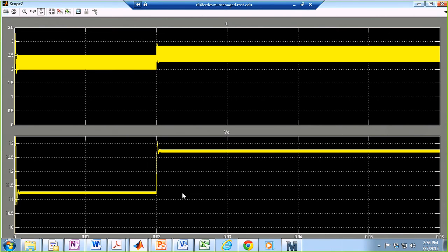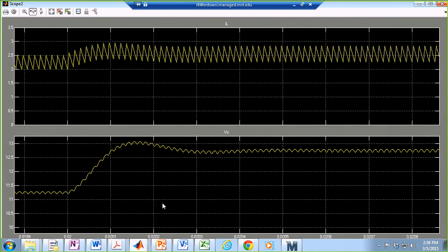So this is an open loop behavior, and as you can see, there is also a kind of transition going on. Before, under a steady state condition, Vout was duty cycle times Vin. After I reached a steady state condition, again, Vout is duty cycle times Vin.